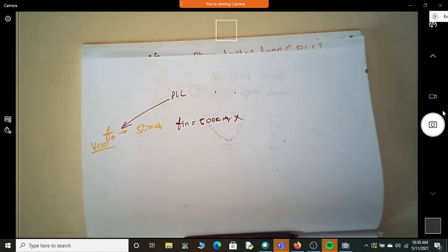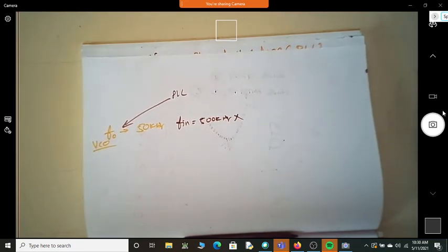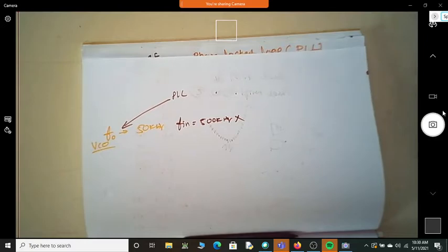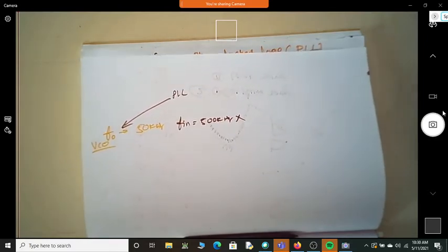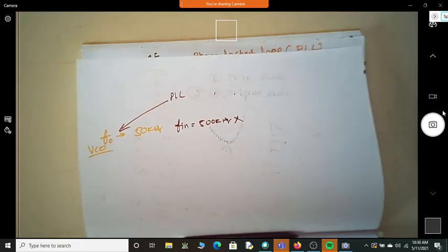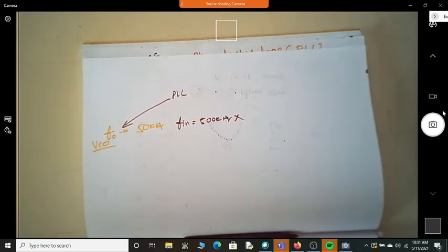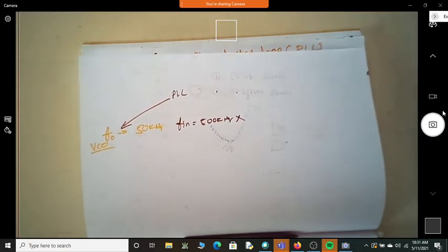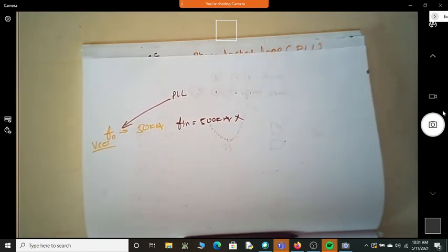So I have also talked about frequency modulation. What is that? Perfect. Now can you see there? Is it easy to detect the amplitude change? What are the major advantages of amplitude modulation? The major advantage of amplitude modulation is that its detection is the easiest. You simply have an envelope detector, you can detect the envelope, correct?